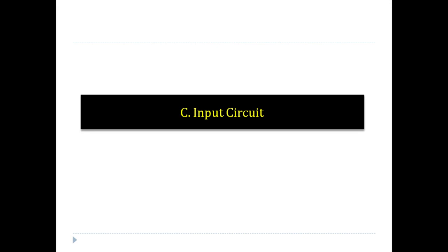Hello everyone. In this video, we are going to talk about input circuit in VLSI chips. Input circuit is an important and integral part of VLSI chip design. It basically has two functions. One is protecting the digital logic from the external voltage trace and noise. Voltage trace is basically caused because of the electrostatic discharge, because of both human, machine as well as packaging.